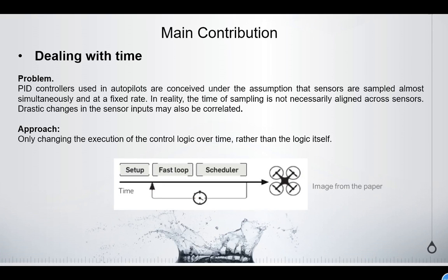The second issue is about timing. The system's hyperperiod is calculated as the minimum time interval for all sensors to be resampled, based on the sample frequencies of each sensor in the system. After first identifying the conditions under which the control loop needs to be executed, it needs to wait until the current hyperperiod is completed.